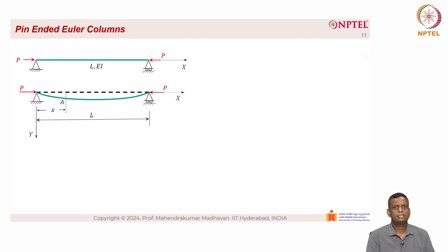So when it reaches the critical load P, there is a deflected shape that you can see here. There is a small distance at which we will take the equilibrium, that is at point A. The distance from the left end is x. So when we look at it very closely, we have this deformed shape to be precise. We have point A, the length is x from the left end, and the deformation in the y direction is v. So the forces that are acting are P here, and the internal resisting moment Mi is acting as shown here.